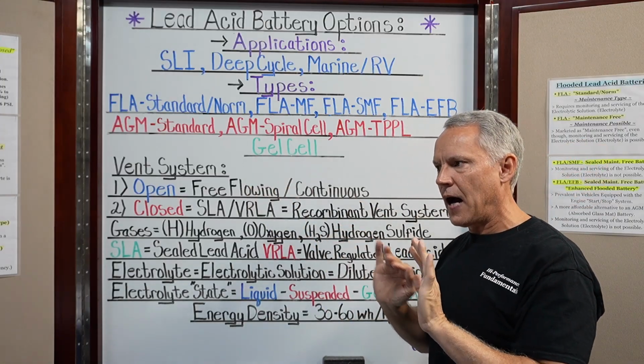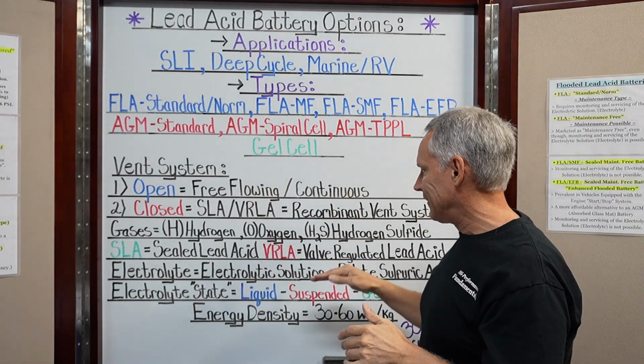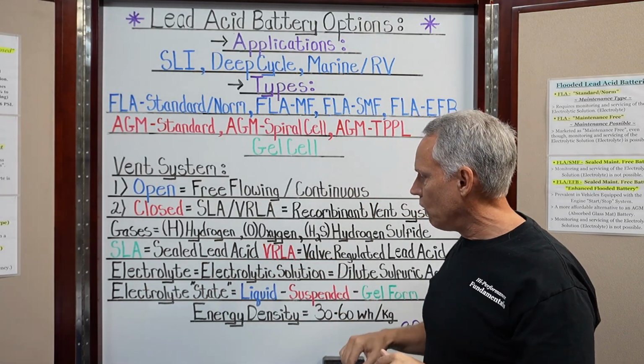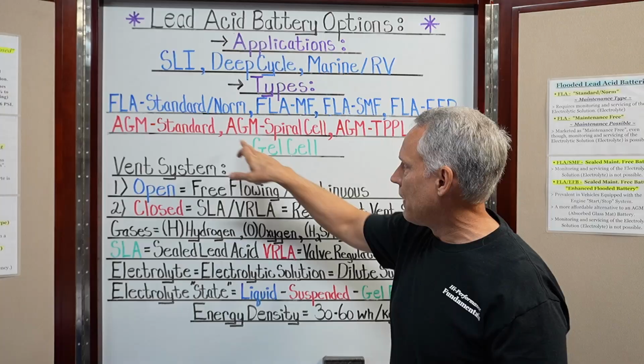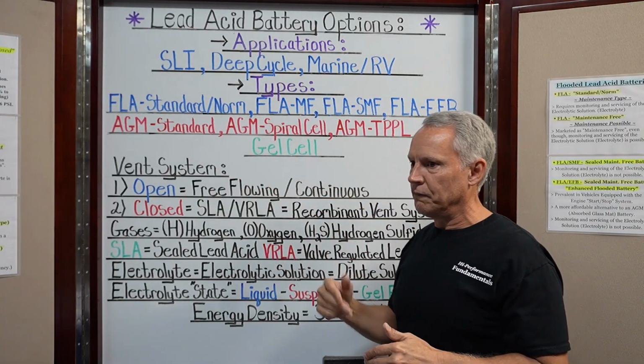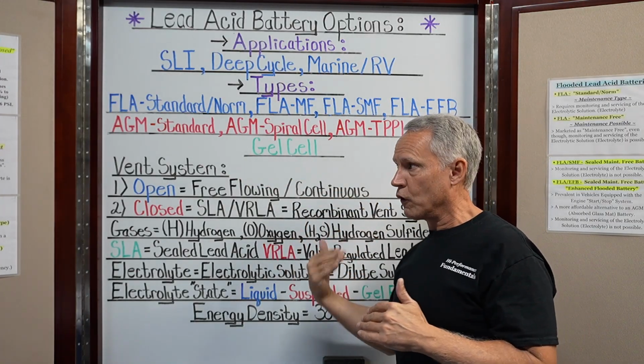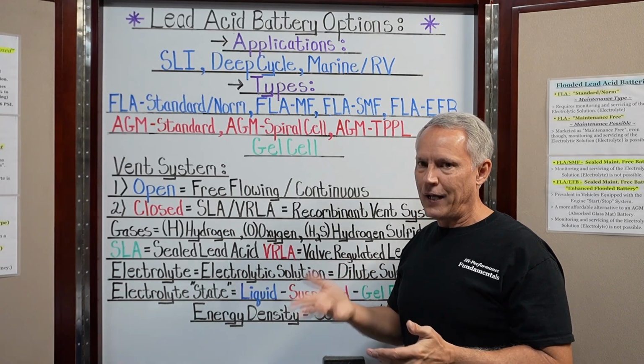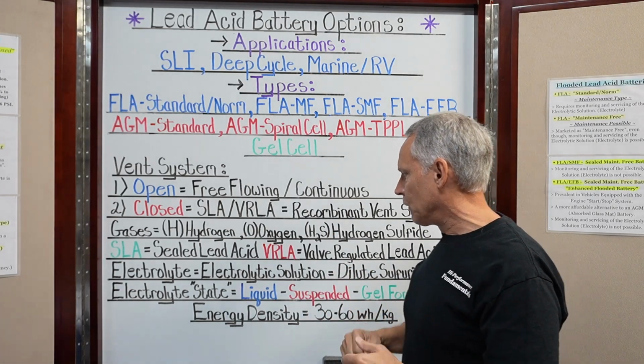But you still vented hydrogen and oxygen gas, right? So basically you're depleting the water level in this sealed battery. You can't put it back. So never overcharge a sealed battery. If you overcharge it and you start to vent those gases, depleting the water content in the electrolyte, there's really no fixing it. You're damaging the battery. You can't go back and fix it. That's what I want to be known.